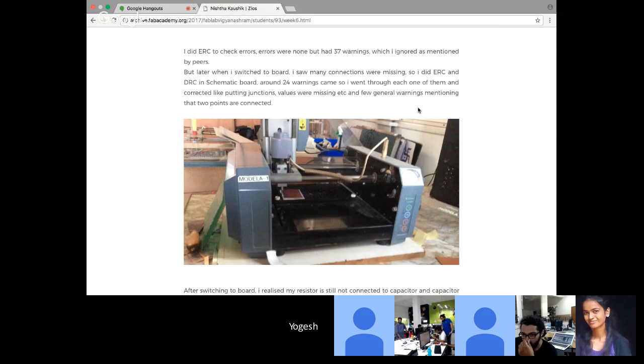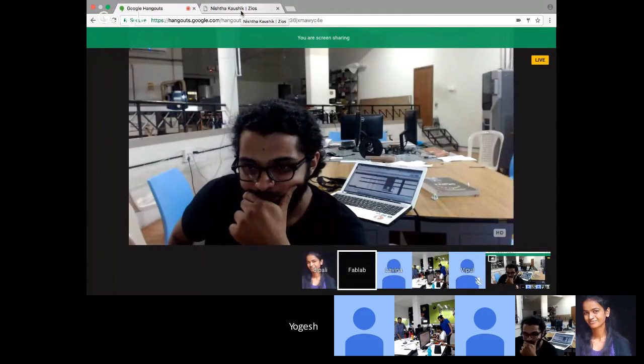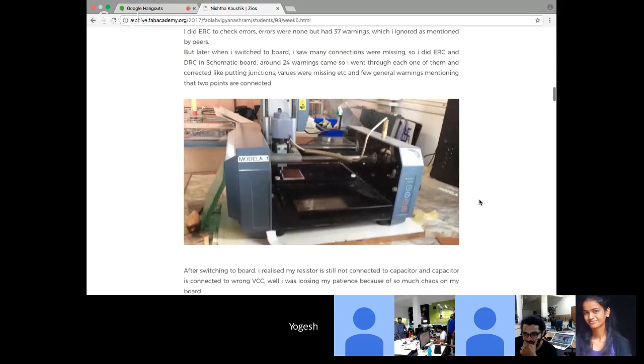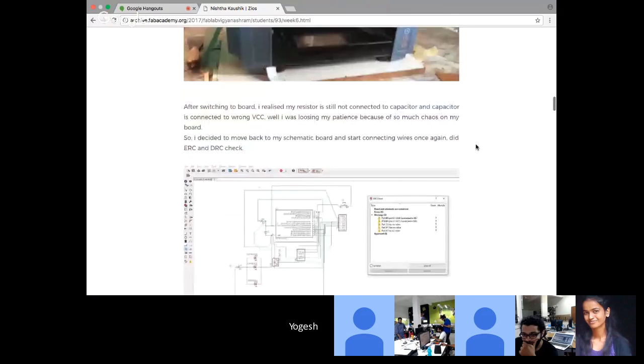When I went back to the schematic, I did ERC. First of all, the mistake I made was that I ignored the warnings in my first trial, because I got to know that warnings can be ignored. But when I saw in my board that a few connections were not there, I went back to the schematic, did ERC again, and went through each one of the warnings and followed it. There is one more tool that you can use, which is known as show.